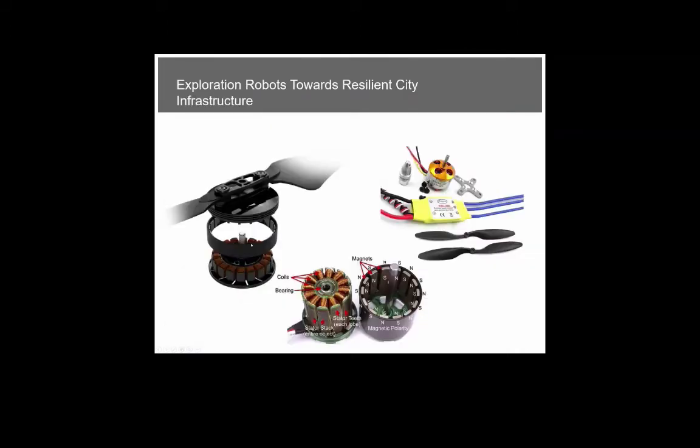Even in the motors themselves, if you want to understand how things behave, how a certain signal to a certain motor causes a certain change, you need to understand how they work. Here you have brushless motors. Brushless motors in drones are just coils inside magnets, and you have a controller in there. The real elegance of these modern systems is that they are self-contained, plug and play packages. The speed controller is a nice small controller that plugs into the motor and makes it work in the right way. So the beauty of it is that they are well packaged.